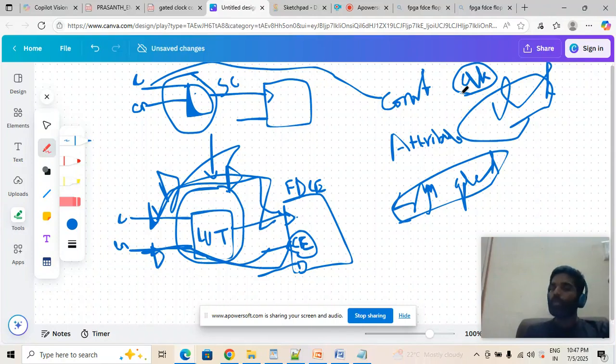If you have more than one clock, in some cases we'll have more than one clock in our constraint, clock one, clock two, and so on. I don't have to do the clock gating on all the clocks. In some cases, we can write the attribute in the RTL module itself, saying which clock should be considered for clock gating conversion.